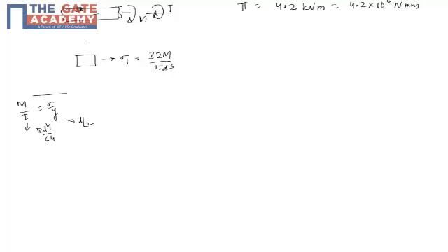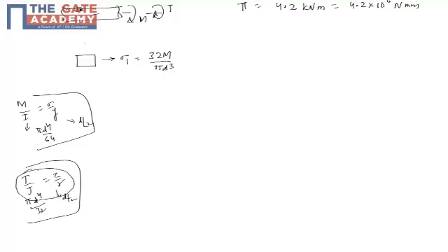That is from the bending beam equation, as well as from the torque equation, T by J equals tau by R, where J is the polar moment of inertia of the cross section, pi d power 4 by 32, and R is d by 2. You get the maximum shear stress due to the twisting moment of the shaft.